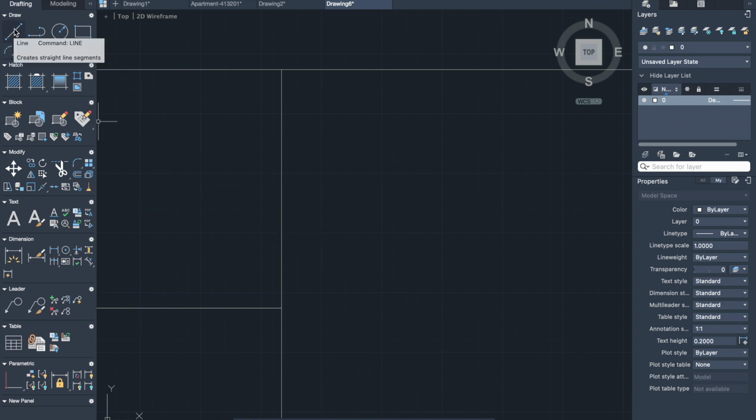So if we go to our drawing line here, now like I said before, if I have the snap to object snap function on the bottom right hand corner, if I want to click on this midpoint, it's actually going to bring me up to that top line where it's snapped. If you can see the green arrow. So if I exit out of here and then I go down to the bottom and I turn off that object snap, now when I go up to the line in the top left hand corner, if I hold shift, I can create just a straight line across.